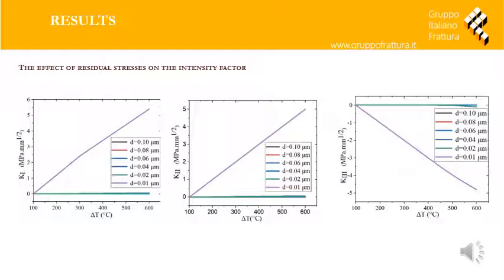The results obtained in this part of the work show that under the effect of residual stress, a crack initiated in the matrix propagates in pure mode I when its front is located relatively far from the interface with the particle, and in mixed mode I, II and III when its front approaches this interface.